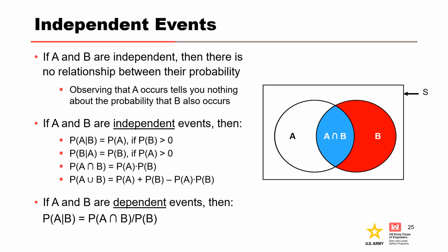Another example where independence would not be a good assumption would be for a dam that has two separate embankments that would overtop at the same time, but where one is much more erodible than the other. If the more erodible embankment breaches first, the overtopping hydrograph of the other embankment changes. So the probability of the less erodible embankment breaching would be dependent on if and when the more erodible embankment were to breach.